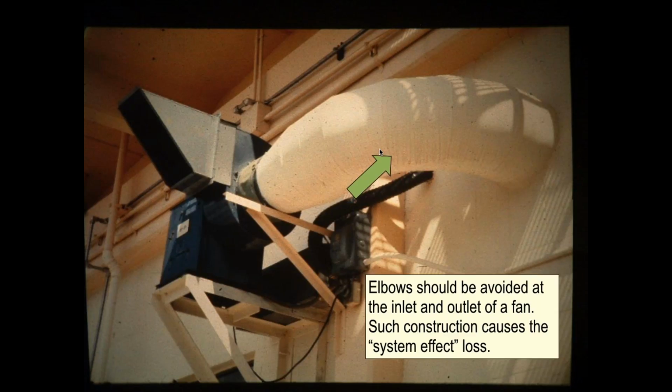No, I'm saying sometimes you just have limited space. Yeah. Well, yeah. You want to know something? How many of these pictures are you going to see that have a turn right at the duct, right at the fan? A lot of them do for exactly that reason. They have limited space. Right. But good practice is more efficient. You can use a smaller motor, use less energy, if you avoid this.